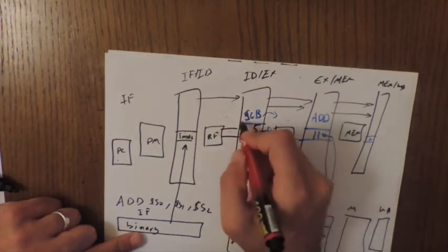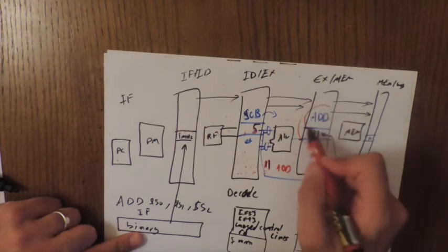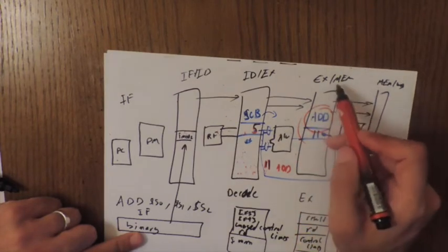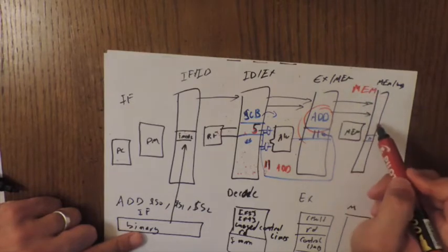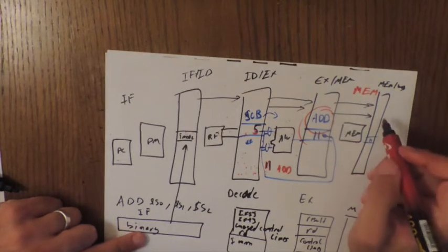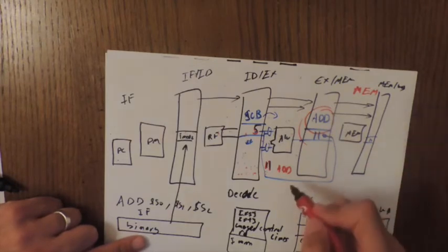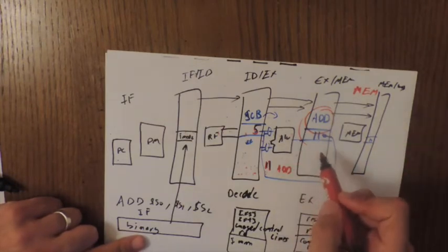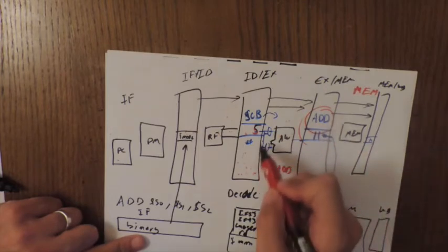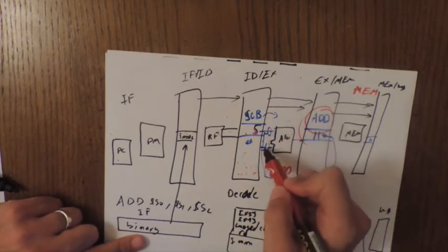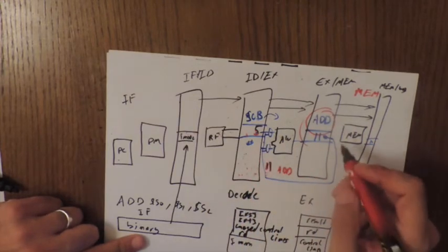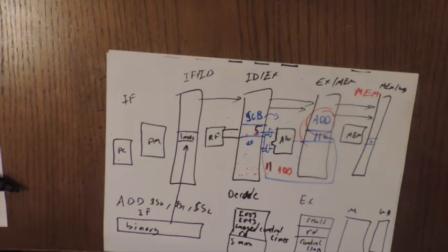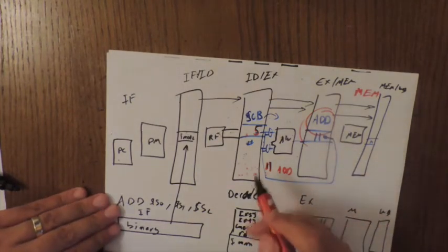This is from the add, and now the add is being propagated through the memory stage, because this has nothing to do with the memory. We're not doing any load, and now I can actually use this value in either RS or RT. This act is called forwarding. Of course we're going to discuss the hardware later, but this is the way of passing a value from a stage